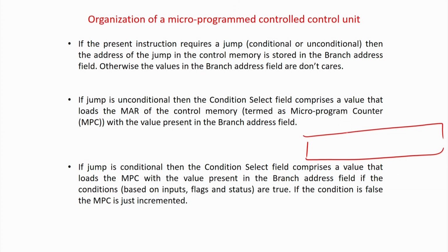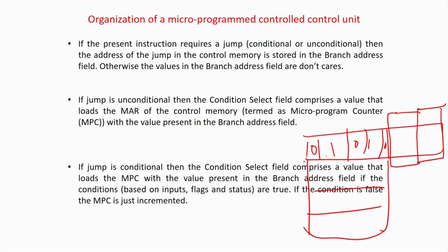The microprogram is nothing but some parts of a memory. So I am filling the values 0, 1, 1, 0, something like this has been filled up. Now I have to reserve some part here and some part there. I will tell you why these things have to be reserved, because otherwise it will go in sequence. It will keep on going in sequence one after the other, first this location, this location, this location, and so forth. Now say that I want to go from this memory location to this memory location, that is, this is the present state, and for the next state I have to go not to this but to this, some other memory location.